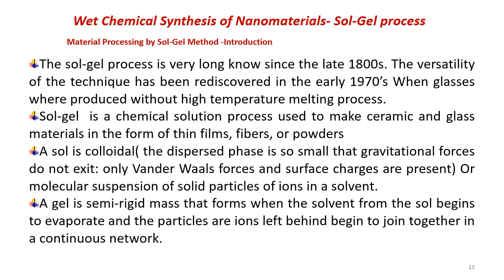As we have known, in the bottom up approach there are two methods, that is the liquid phase method and the gaseous phase method. Under the liquid phase we have the wet chemical synthesis of nanomaterials, that is the sol-gel process. Material processing by sol-gel was introduced and well known in the 1800s itself. There are varieties of techniques and rediscovery happening in this technique.